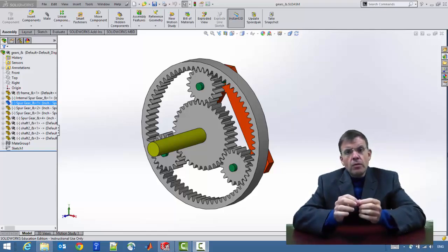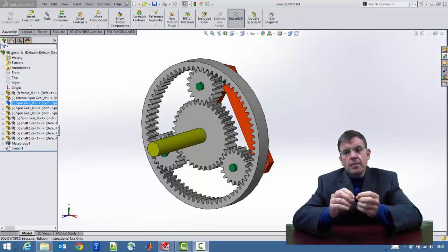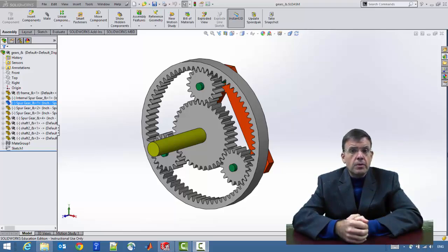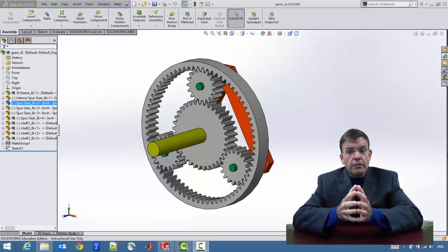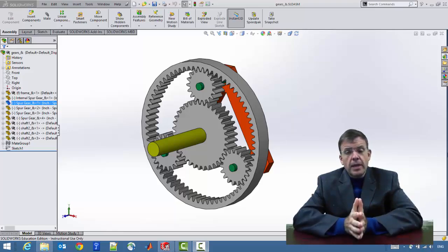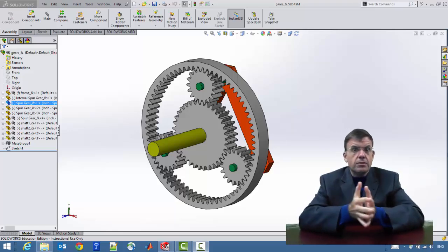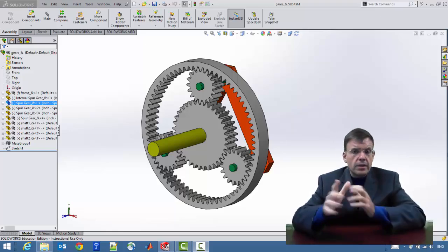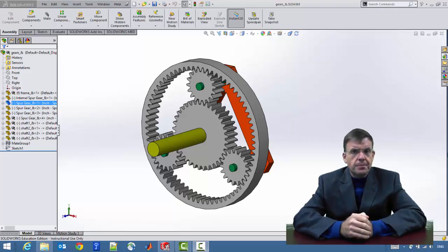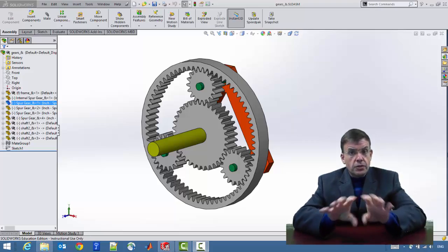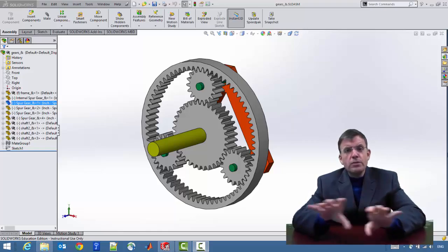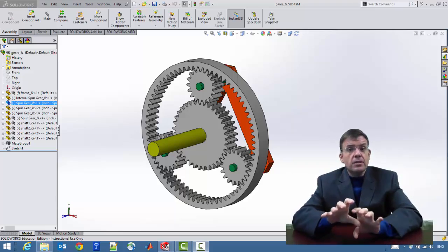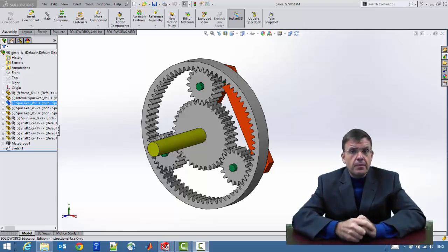Mechanical mates extends that capability in the cases, for example, where there is a gearing ratio between components. That's one very specific example of mechanical mates. There's also cams, there's also slots, there's also universal joints, and others yet. And we'll take a quick look here at a couple of them. So first of all, the good news is you're getting the wonderful power of a kinematic engine in there just through conventional mates.